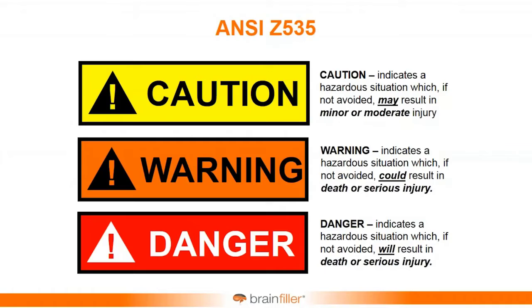There's been an evolution with this, because in the early years, a lot of people thought, well, an arc flash hazard could potentially kill you, so we better put danger on everything. The problem with that is if you use the red danger on every label, pretty soon it loses its meaning. You walk into an electrical equipment room, and it's like, oh yeah, that red thing, that's on every piece of equipment out there. So taking a step back, people began to recognize, let's use orange and warning on everything up to 40 calories per square centimeter. And I'll talk about the 40 calories in a bit.